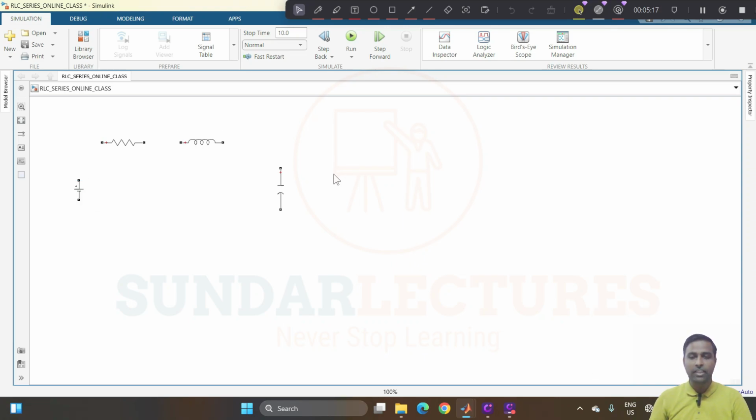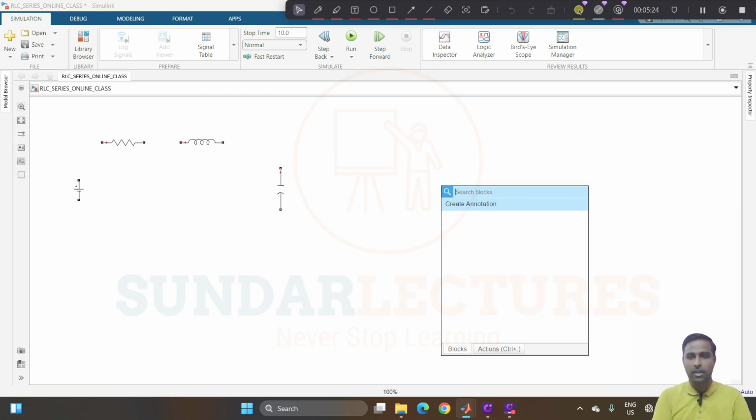Now we have got everything, but we need to measure the current and voltage. So again double click with the left side of the mouse, and you can see this block. Here you search for current measurement.